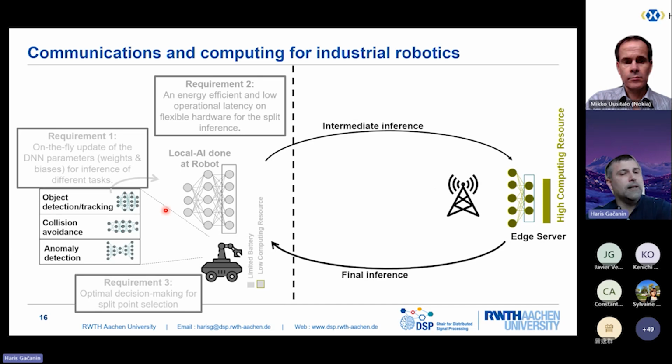Okay. If you are looking at mobile robots, it depends, right? It depends whether it is a small device or a huge device. Depending on the computational complexity, we have some devices that we are using. Some of our mobile robots work with models for deep reinforcement learning that are ported on 540 kilobytes of memory. On the other hand, we have some deep neural networks that consume much more, and we need to prune them and really reduce them.